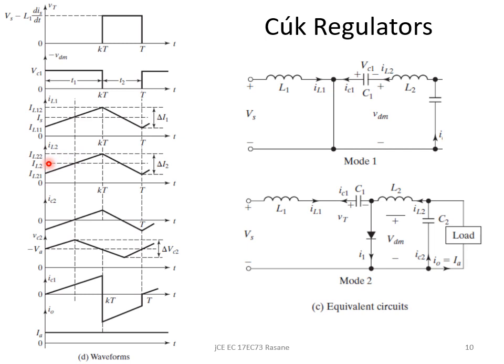Okay, and the average value of this is equivalent to the load current, that is inductor current IL2, I would say. So IL2 will be the average value, and delta I2 will be the ripple current that is going to flow through this L2.